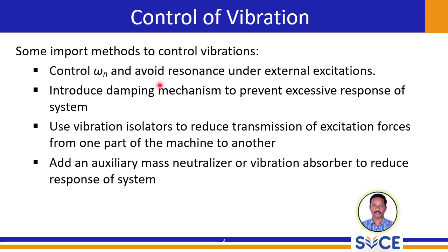resonance. Resonance occurs when the frequency of an external excitation force is close to the natural frequency of the system. This can lead to a dramatic increase in the amplitude of vibration, potentially causing damage or failure to the systems or structures. Therefore, by carefully designing our systems to have natural frequencies that are far from expected excitation frequencies, we can significantly reduce the risk of excessive vibrations.